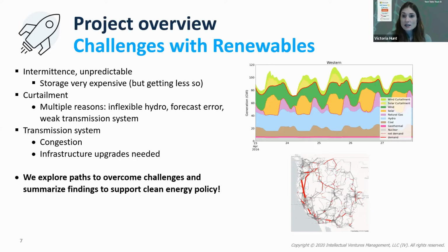And in this case, we have a phenomenon called curtailment. So curtailment is a reduction in the output of generation of what a generator could otherwise produce because it is more than what's needed by the demand. So for example, on this plot on the right side, you can see that there is a time series in the upper right corner. The neon colors are visualization of electricity that is generated by renewable sources that is exceeding demand at a given period of time.